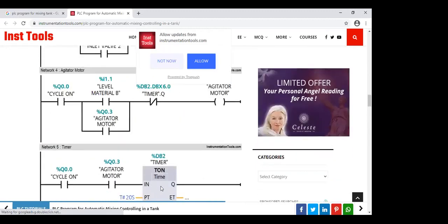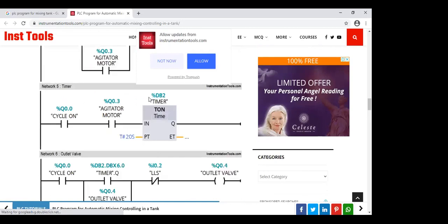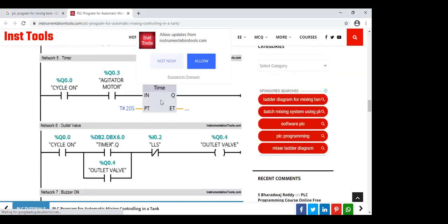You have to have a timer. It's just that how you configure the timer is different. But the ladder logic is basically the same. And how you address the timers and the inputs and the outputs: the dollar sign, the percentage sign, and so forth.